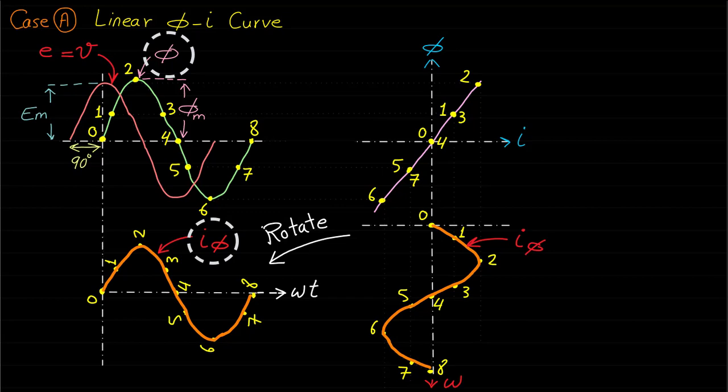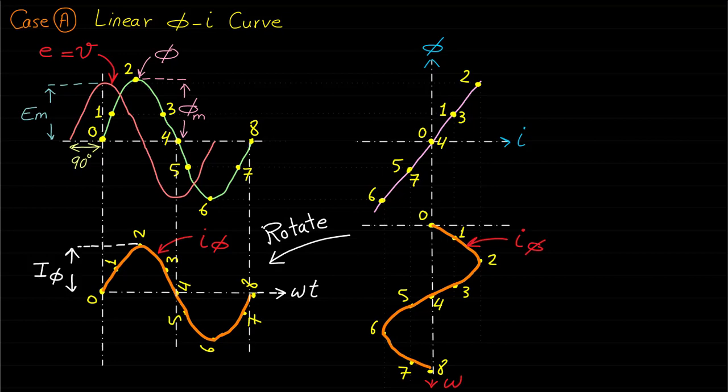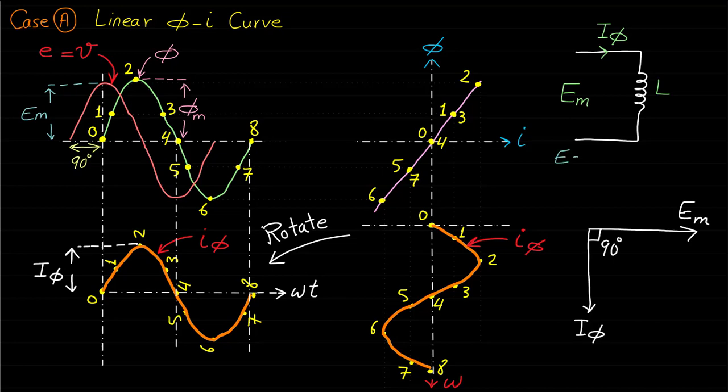It is obvious now that when the BH curve is linear, or the magnetic circuit working within linear region, the excitation current is also sinusoidal and has no harmonics. In other words, the current required to produce the linear BH curve has no harmonic and is changing sinusoidally. The equivalent circuit and vector diagram of such case are as follows.